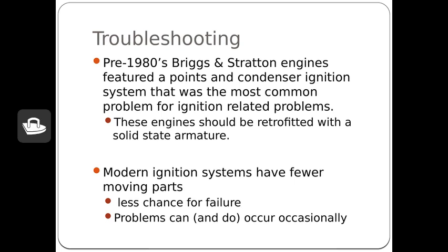Briggs pretty much recommends that retrofit kit to introduce a solid-state armature to those older engines, and once that's accomplished, there's very little to go wrong with these modern ignition systems. Nevertheless, problems can and really do occur because we have moving parts, we have mechanical systems, and we still have human error.